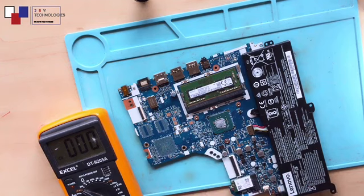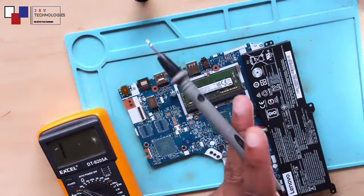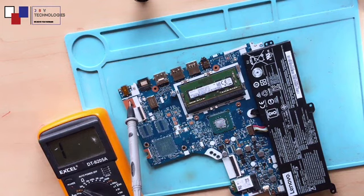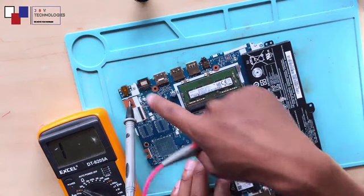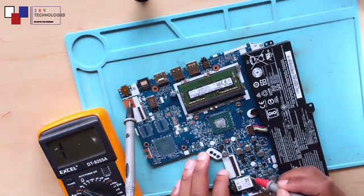Here we are, 00. So what you do, you connect one probe to ground, into a screw hole. Screw holes are ground. You touch the screw hole with a multimeter probe, like this. And the other one, you touch pin number 31. You should see a light here. If you see another light flashing there, let's see.